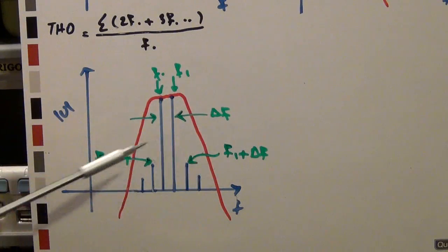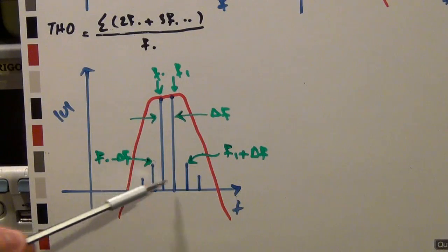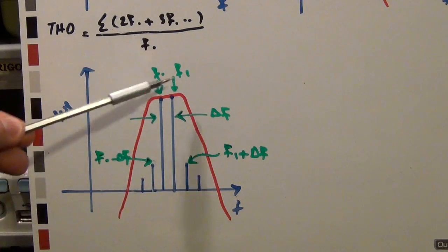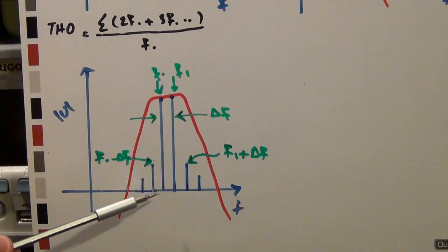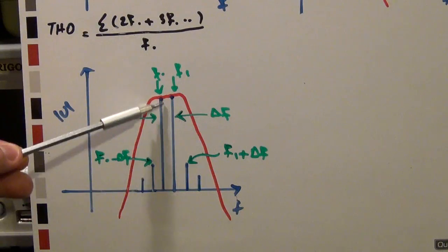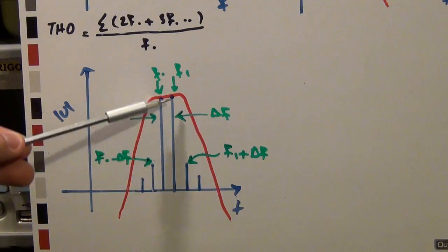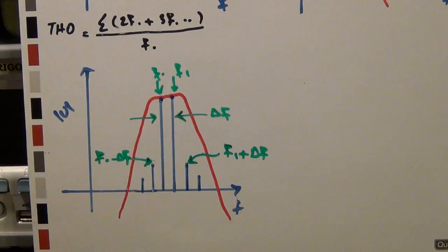And this is your channel, meaning that you're saying I'm going to occupy, let's say, channel 11. And channel 11 only gives you 100 megahertz, so your signal has to stay within 100 megahertz of your center channel. So how can you measure the total harmonic distortion, or in this case the IP3? You would put in one tone at F0, then you put in another tone at F1, and the distance between those two tones in frequency we call delta F.